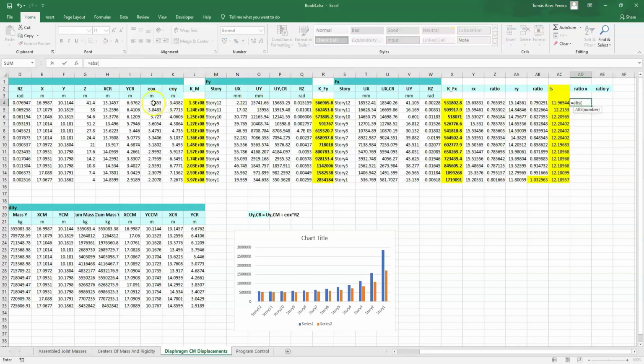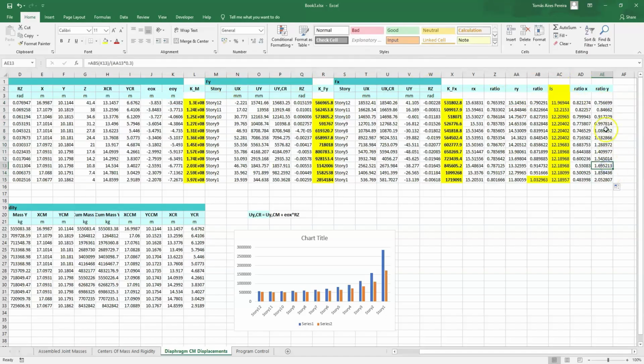Basically, we're going to directly include the eccentricities calculated earlier related to the Rx factor. And we will also directly include the 0.3 factor so that the expression is comparable to 1. Below a value of 1 in these expressions, we are fine. Above that value, we are not. In that case, we do not satisfy the Eurocode expression.